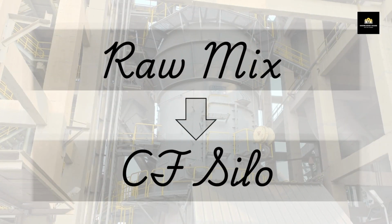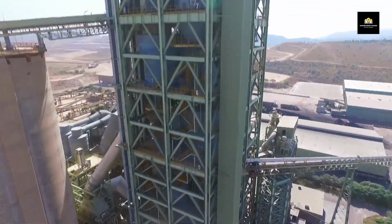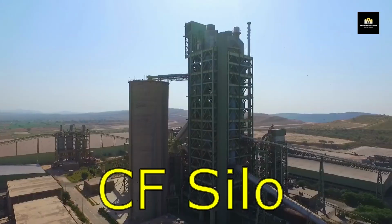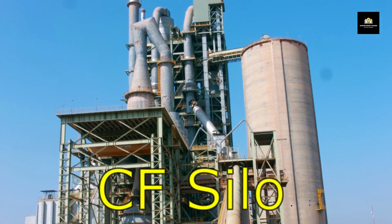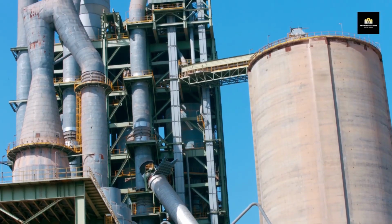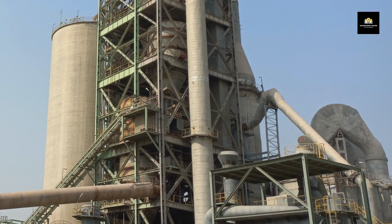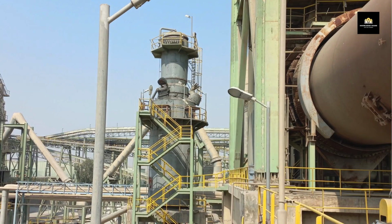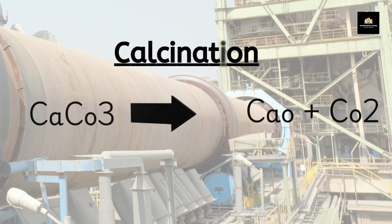After grinding, the powdered raw meal is fed to CF silo. CF silo or blending silo is an intermediate storage of raw mix before feeding to kiln through preheater. The raw mix is heated in a preheater tower using hot gases from the kiln. This begins the process of calcination, where carbonates in the limestone begin to decompose into calcium oxide, lime.